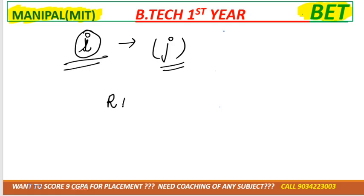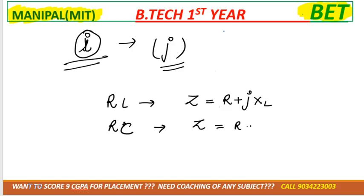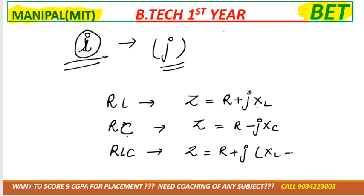So if it is the combination of R and L, then the impedance formula we can write as R plus JXL. If it is the combination of R and C, then the impedance formula is R minus JXC, because for RC it is minus, and for RL it is plus JXL. And if it is the combination of RLC, then Z equals R plus J of XL minus XC.